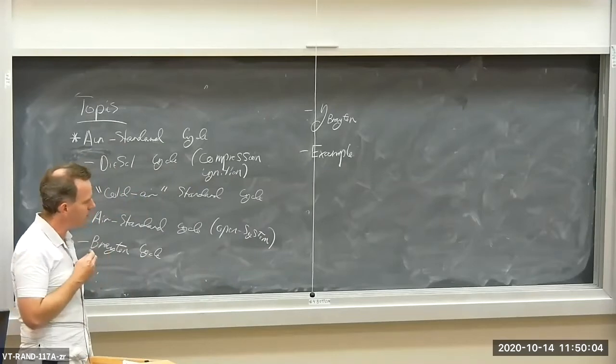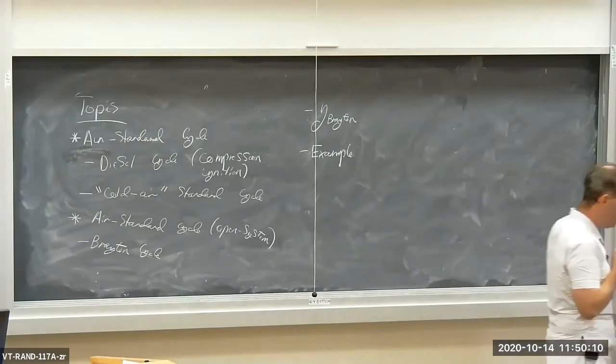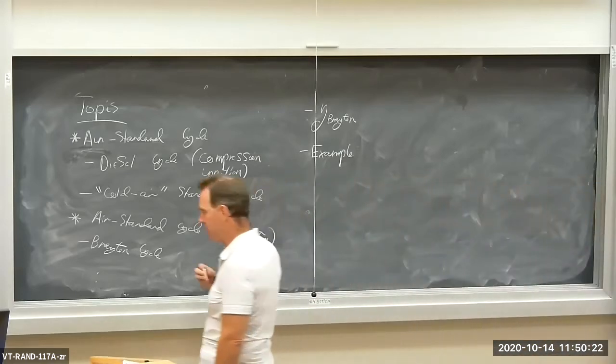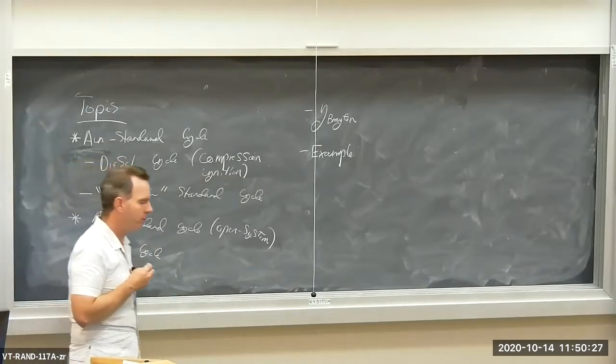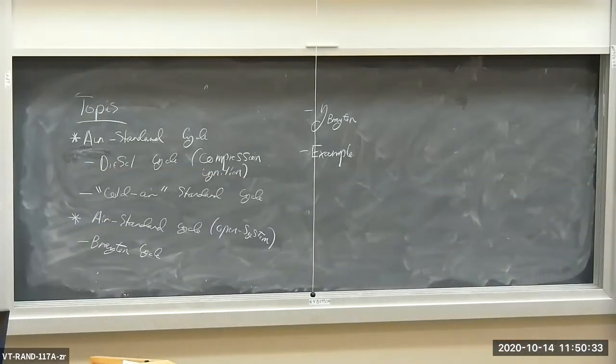Open system here is going to be using shaft work as the output. And then we'll see if we can do a little example, or at least get started on an example, involving a Brayton cycle. Okay? Indeed, we'll relax some of our assumptions about internally reversible processes. We'll deviate a little bit away from the air standard assumption, and we'll assume that the compressor and turbine in the open system Brayton cycle are not 100% isentropic efficient. There'll be some irreversibilities in the cycle. So that'll be a little bit different today.